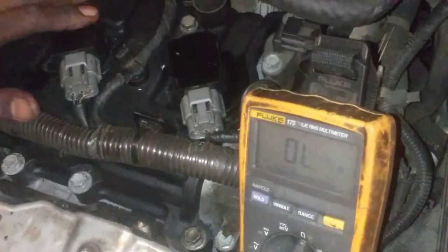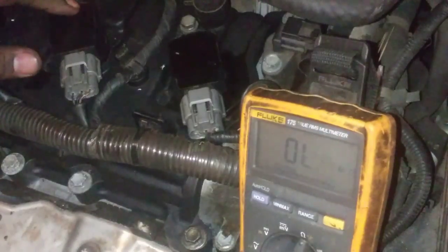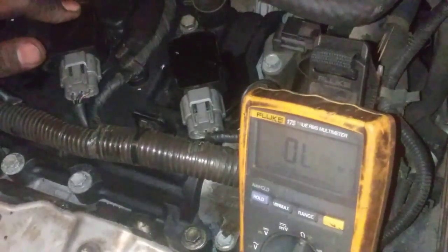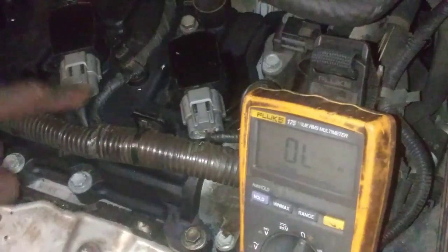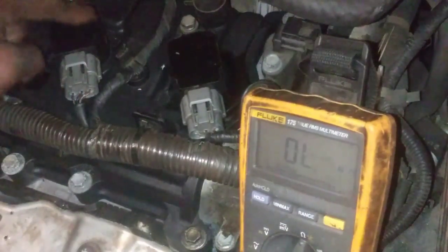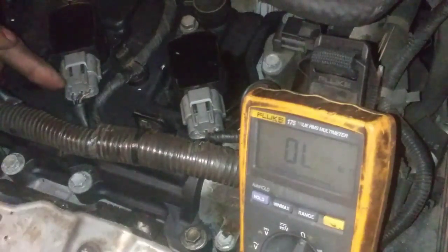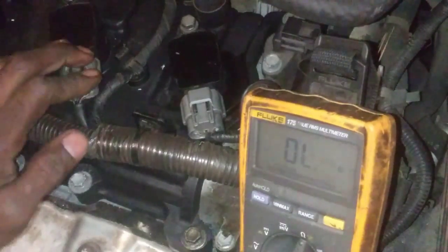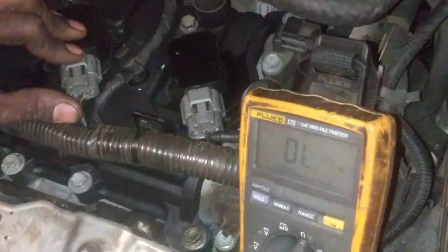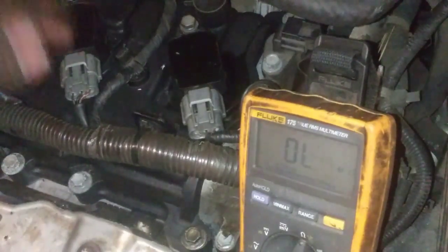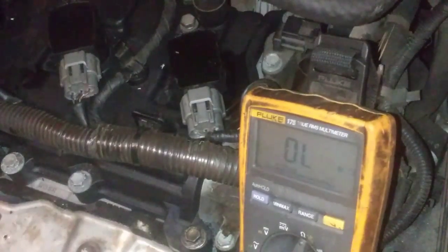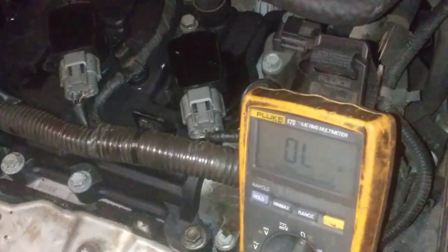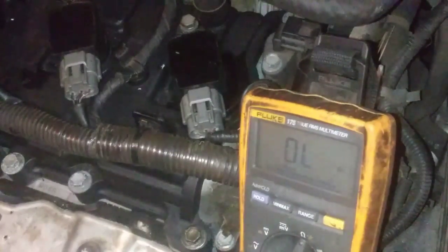Strange. I'm not going to ask any questions, but obviously that computer was in the midst of failing, and there's just no way a fusible link that supplies power to this unit will cause an internal short to a signaling side going to the computer, unless that computer was just failing. That's just impossible. I mean, there's resistors in here. It's just a transistor. Crazy, but it's fixed. It's working. We were able to program the key with the MS906BT on this 2008. Very useful.